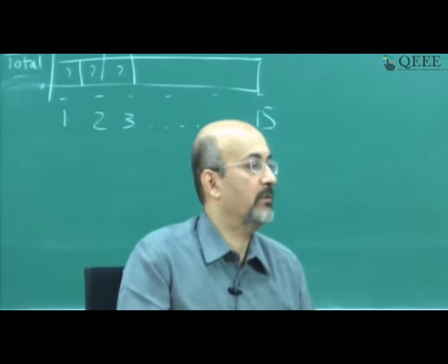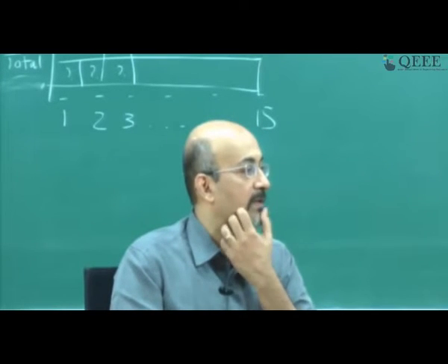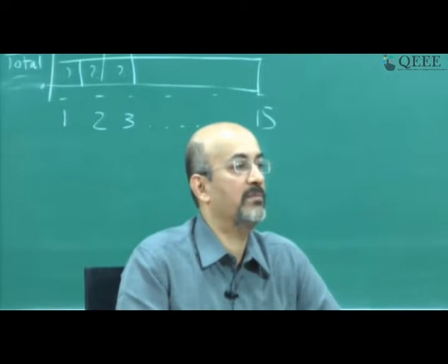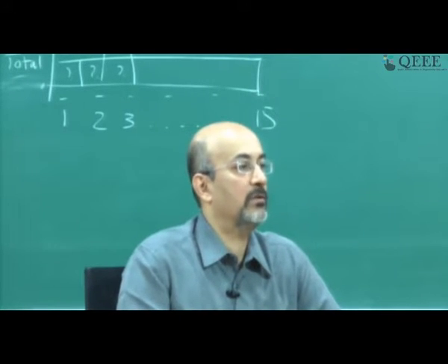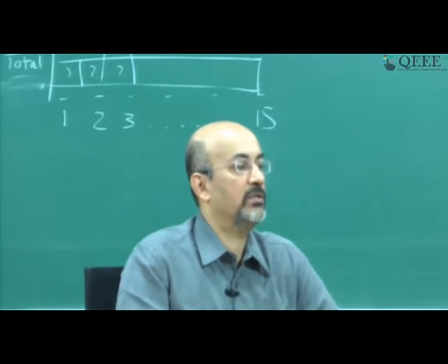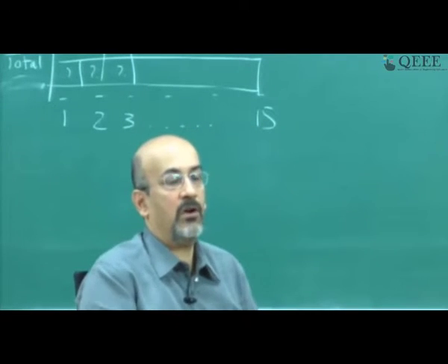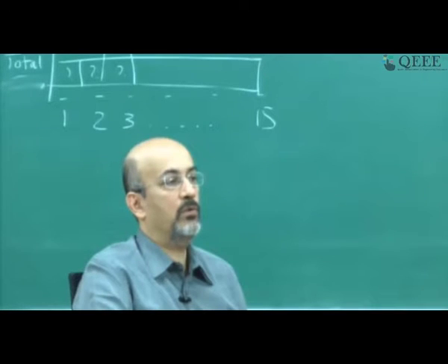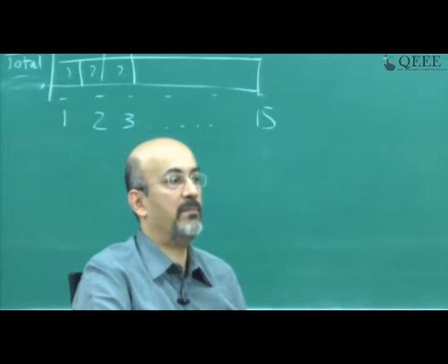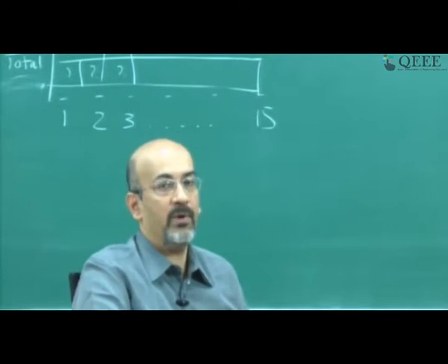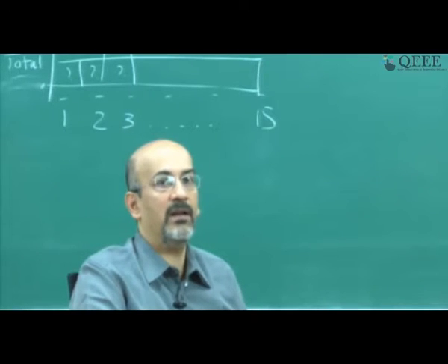Next question: what are the uses of cumulative cash flow? With cumulative cash flow, managing money becomes the most important. Here we have shown just over-allocation. I'm going back to where I'm showing all three cash flow diagrams. As a contractor, do I want to spend my money later or spend my money earlier? In many cases, I would like to spend my money later because, in a simplistic way, the money can earn interest.